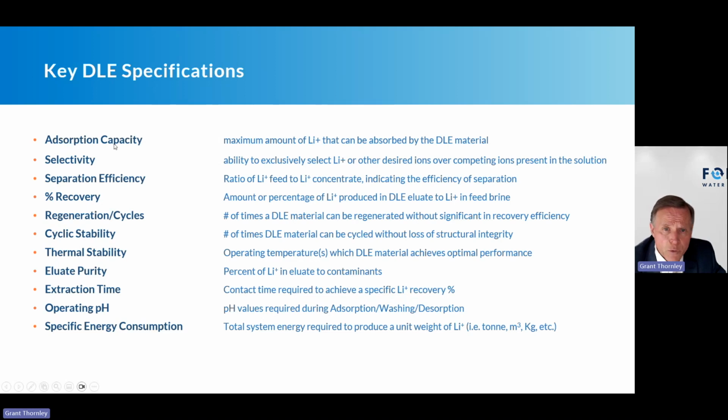I want to know my absorption capacity, how much lithium is being absorbed into the media. I want to know the selectivity, right? I've got lithium, sodium, what other? What's the selectivity range of this? My separation efficiency, my percent recovery.